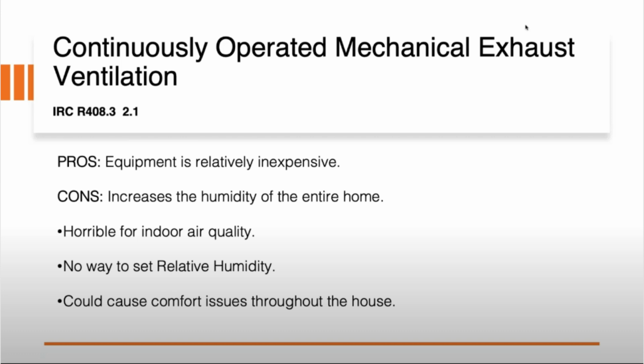Once the crawl space has been conditioned correctly, the air infiltration issues and bulk water issues have been solved. All we need to worry about is relative humidity. What I am alluding to here is the fact that conditioning really means moisture control. The cons with this mechanical exhaust ventilation is it will most likely increase the humidity in the living space of the home in the humid times of the year. I'm going to show you why in just a minute.